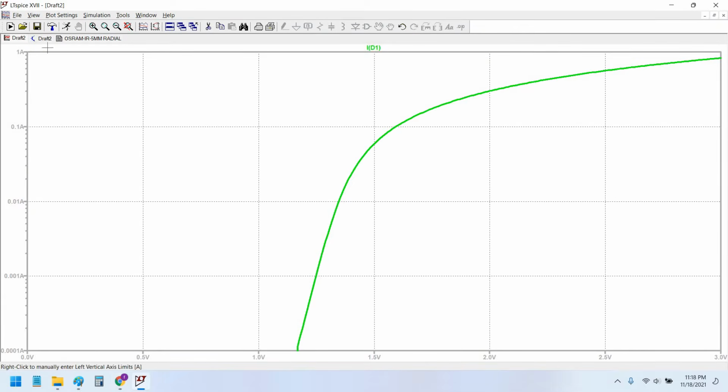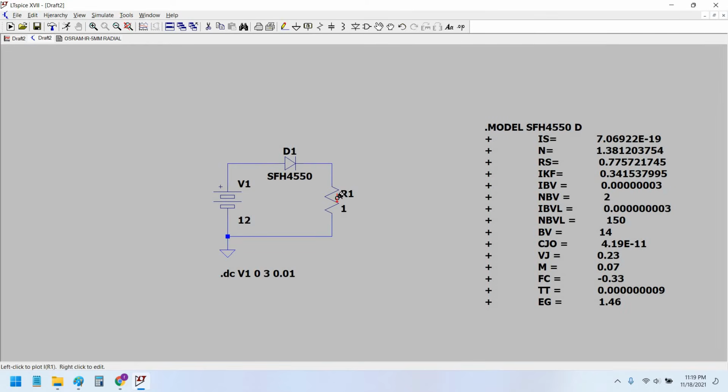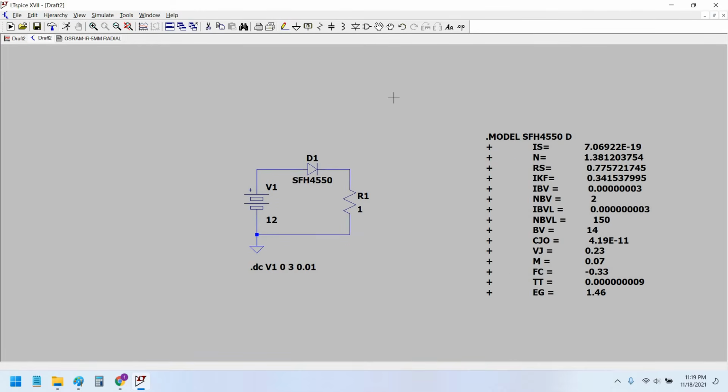Right, now we move on to the constant current LED circuit. For the constant current LED circuit, we need to use two transistors. Both transistors would be NPN BJT transistors. One NPN BJT transistor would be used to drive the collector current to the LEDs, while the other transistor would shunt the base current of the first transistor in order to keep the constant current at the load LED even when the voltage at the input increases.